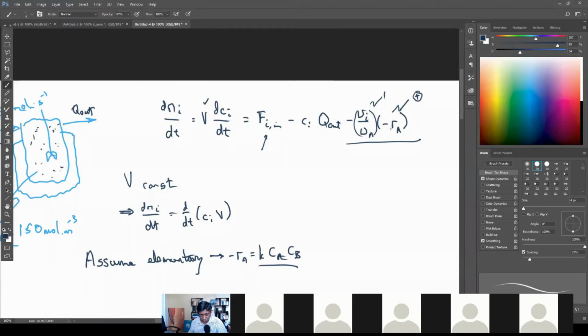We know the stoichiometric coefficients, and we have an expression for Ra in terms of the concentrations. So this looks fine. This is in terms of the variable. There is a kind of hidden variable here. So behind K, that's of course a strong temperature function. So we do need temperature as well, but we anticipate that we are also going to develop the energy balance and get dT dt.